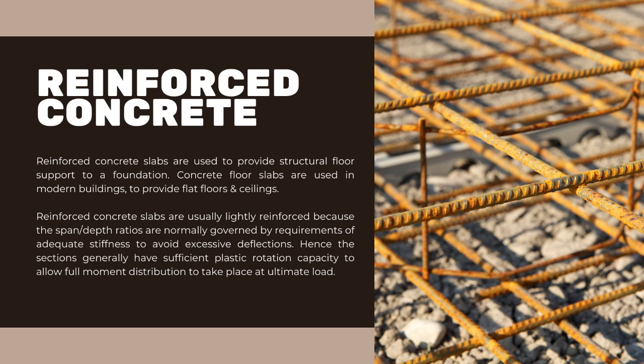Reinforced concrete. Reinforced concrete slabs are used to provide structural floor support to a foundation. Concrete floor slabs are used in modern buildings to provide flat floors and ceilings. Reinforced concrete slabs are usually lightly reinforced because the span or depth ratios are normally governed by requirements of adequate stiffness to avoid excessive deflections. Hence, the sections generally have sufficient plastic rotation capacity to allow full moment distribution to take place at ultimate load.